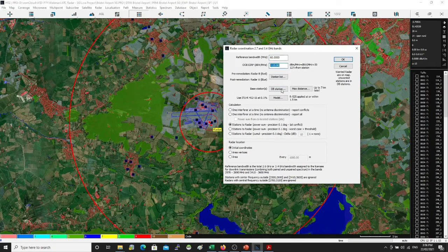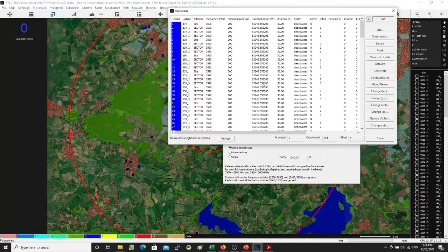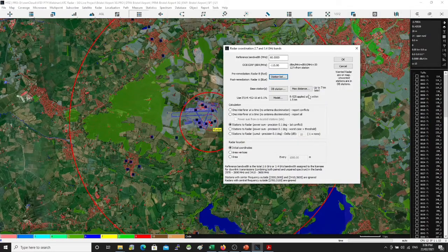So here we have the out of band emissions, and this is EIRP, okay, including antenna gain. The out of band emissions is something you need to extract from your equipment. It could be -90, it could be -110, it could be something else. So this is based on equipment. If you want to use the 3GPP guidelines, then I can guarantee you all the sites will fail. We expect the 5G equipment to exceed the 3GPP requirements. So this is done. 60 meg, you've got here -110.